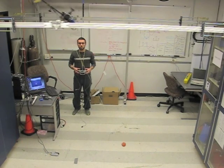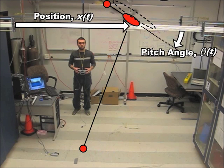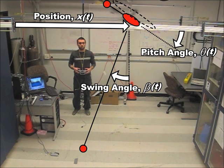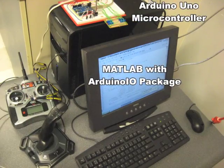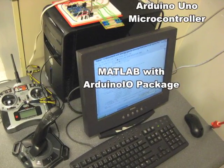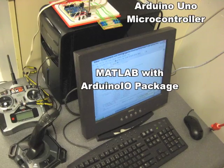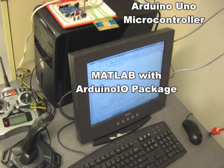For this helicopter system to be useful, we need to be able to measure its position, pitch angle, and load swing angle. We also need to send signals from a computer through the transmitter to the helicopter. These functions are accomplished through an Arduino Uno microcontroller board, which is programmed from MATLAB using the Arduino I/O package, available for free on the MathWorks file exchange server.